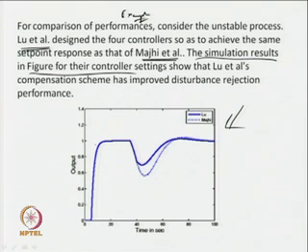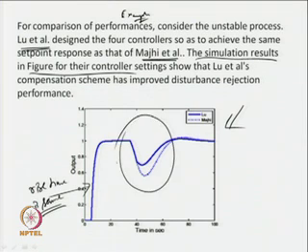You find that for fair comparison again, the same speed of response is maintained. Okay? So, rise time is maintained constant for both cases. Then we do observe that Majhi et al.'s Smith predictor and controller is yielding relatively poor performances, poor disturbance rejections.